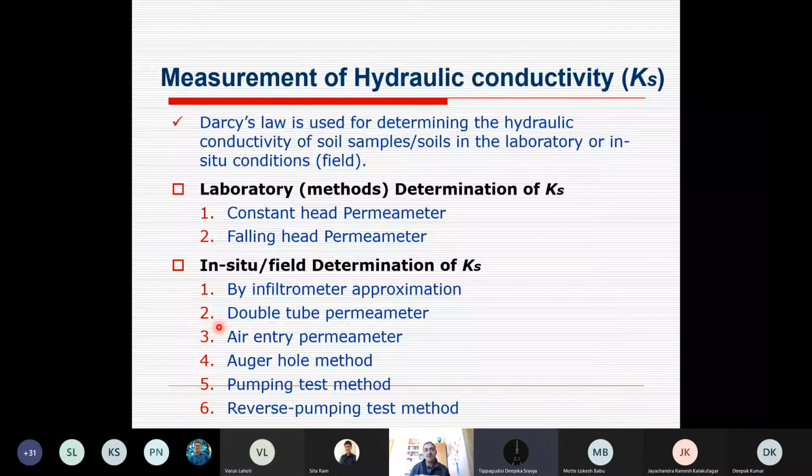If you recall, infiltration characteristics or infiltration of soil becomes constant after a quite long period of time. What does that mean? Means whatever water enters into the soil, it is replaced or it is moving in the same amount of water from the lying soil below the surface. So means what? Water, whatever it is entered, it is moving through the soil as well. So moving through the soil, that is basically hydraulic conductivity.